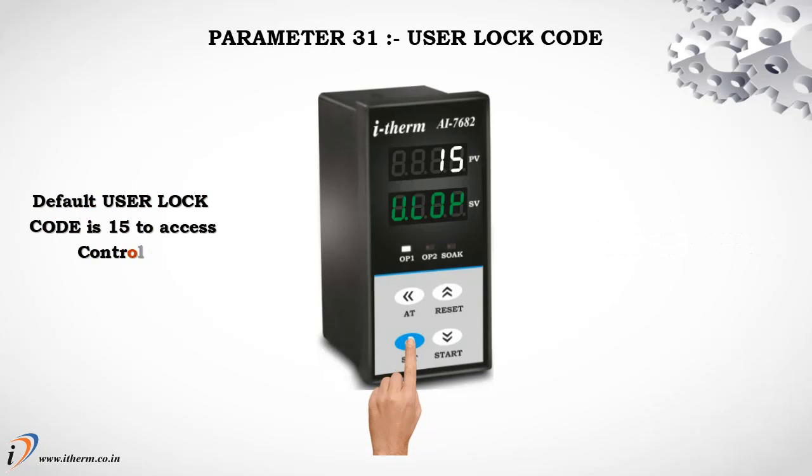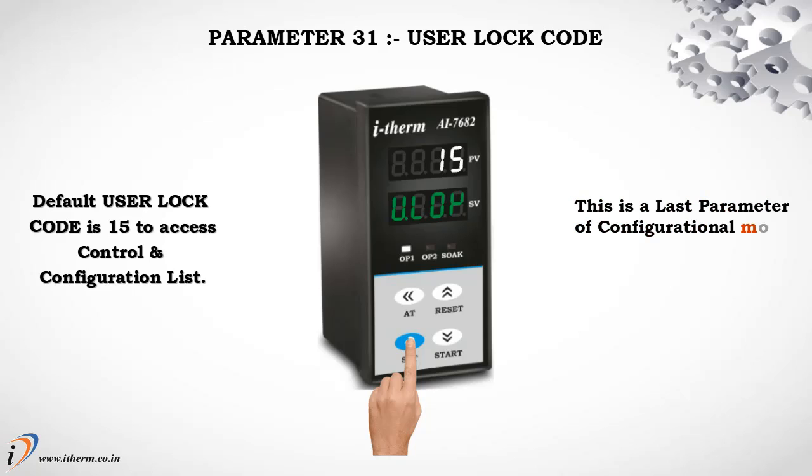Parameter 31, user log code. Default user log code is 15 to access control and configuration list. This is the last parameter of configurational mode. Press set key to enter in run mode.